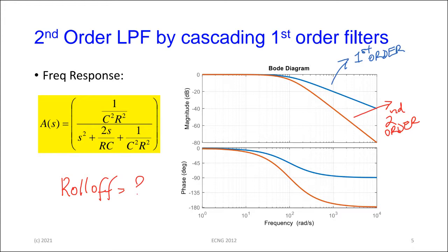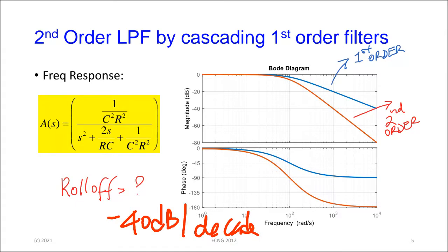You measure it on the graph and you can verify for yourself that it's rolling off at minus 40 decibel per decade. All right, and the roll-off frequency here is, you notice that the phase goes from 0 to minus 180, and we'll talk about that today in signals when we continue our discussion on the Bode plot to see how that phase arrangement actually comes about mathematically.